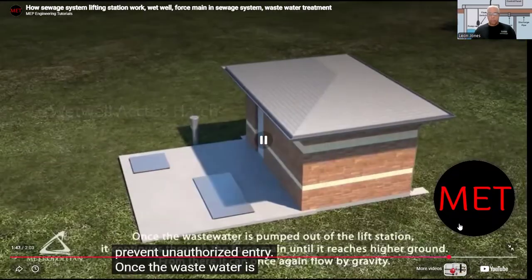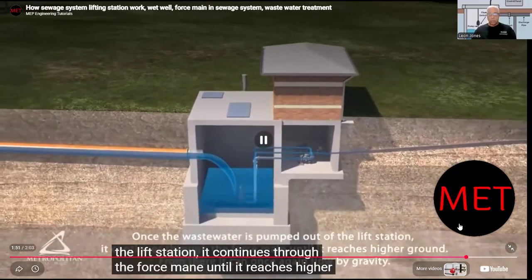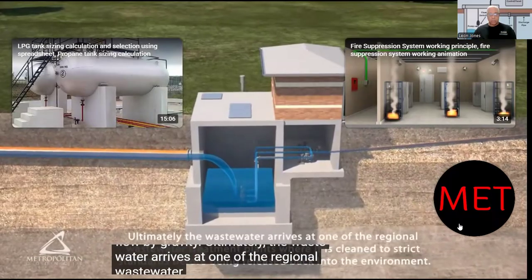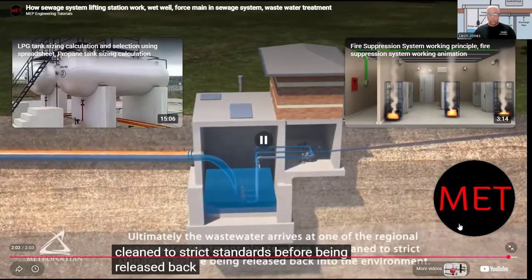Once the wastewater is pumped out of the lift station, it continues through the force main until it reaches higher ground. From there, it can once again flow by gravity. Ultimately, the wastewater arrives at one of the regional wastewater treatment plants where it is cleaned to strict standards before being released back into the environment.